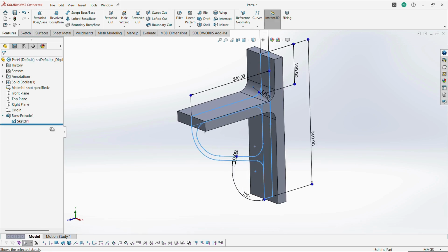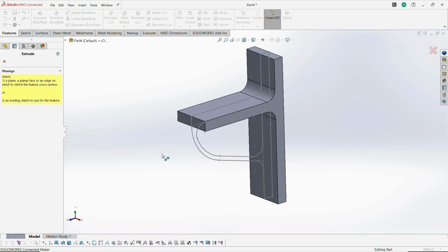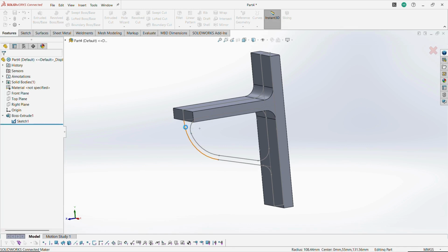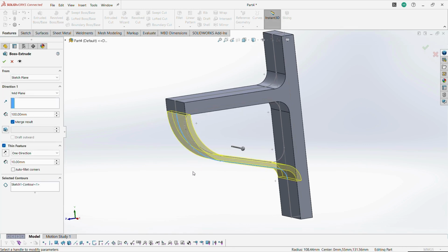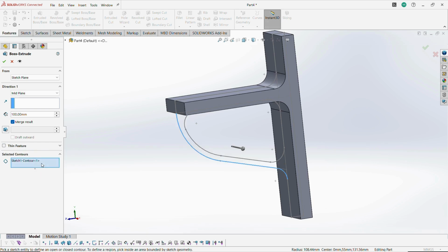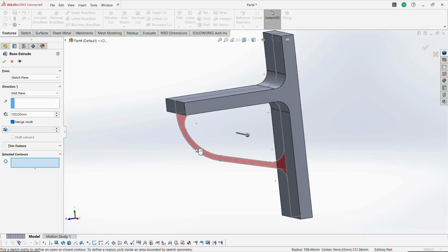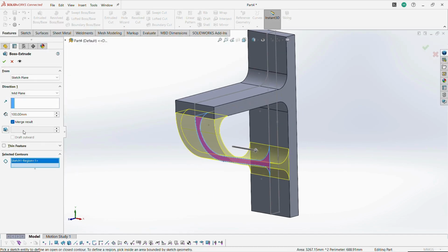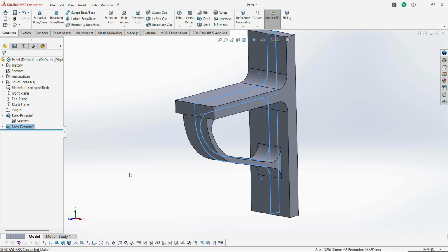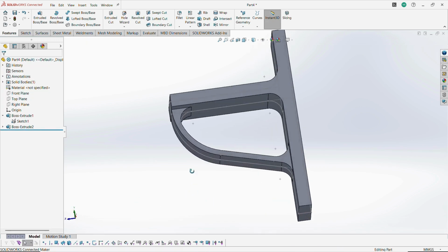Afterwards, using the same sketch profile, we are going to create multiple solid portions. Now selecting this closed portion area, just uncheck this thin feature, right click, select clear selections and choose this particular closed profile to create a solid body under a 60 mm distance. So select this particular one, then initiate the value from the midplane only, 60 mm thickness. The secondary solid body is almost created.